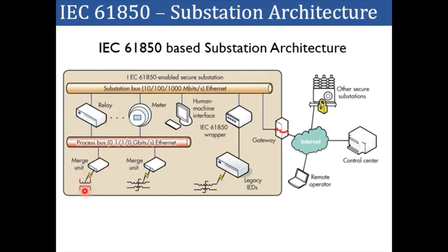So here, if you have the transformer data coming from current and potential transformers, and then it is being shared with the process bus, this information can be shared with the multiple relays and with multiple meters, so that they can take action on the acquired measurement.